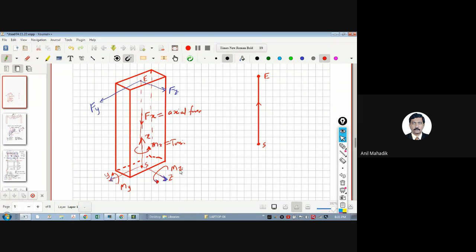So that means you can say that beam or column, the system is same. Along the axis, x-axis, cutting the depth, z-axis, cutting the width, y-axis, and the moments about that axis is the axis of bending. So about z is Mz, about y is My. And along the axis, the forces are along y, shear force Fy, along z, shear force Fz, and along x, axial force Fx. Got all of you?